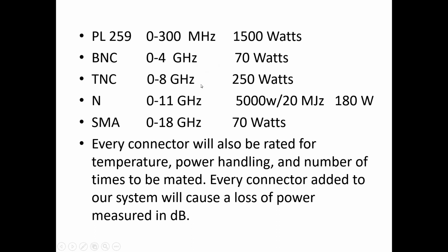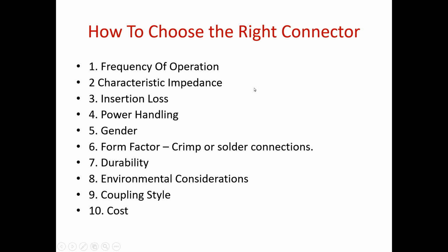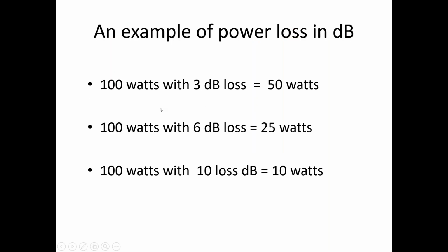Okay, but you can see that as you get into these higher frequencies, change your connector. Some people tell you as you do a wire, get right into an end connector. Okay, right angle connectors, it's not really a right angle. There's a wire in here that's making a very gentle bend, because that's what the RF really wants. How to choose the right connector, look at all these conditions. Cost is always a factor, but if you buy a cheap connector, you're going to get what you pay for. But the frequency is very important. If you know you're going to be in the higher frequencies, do it correctly.